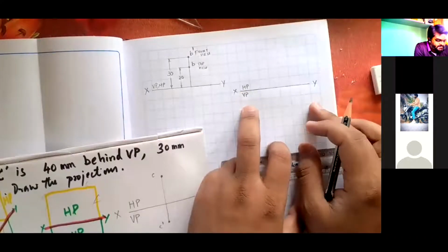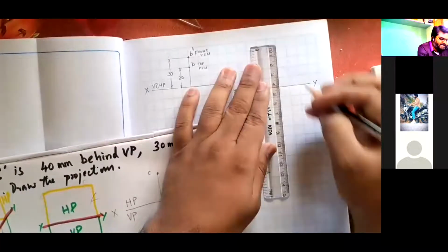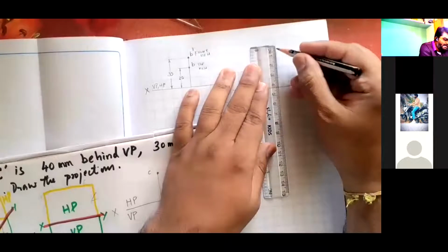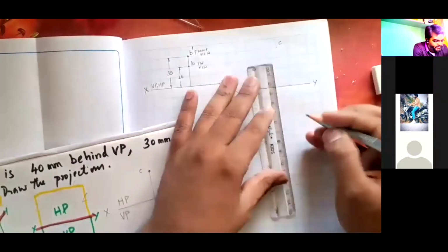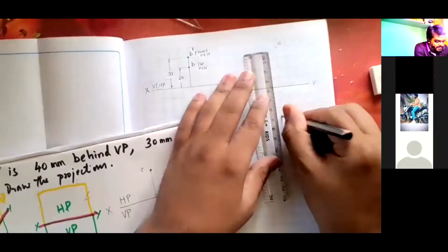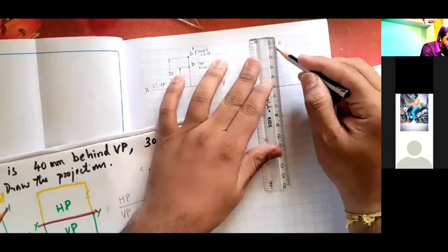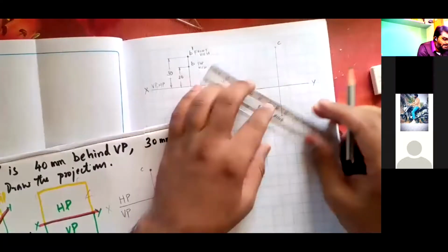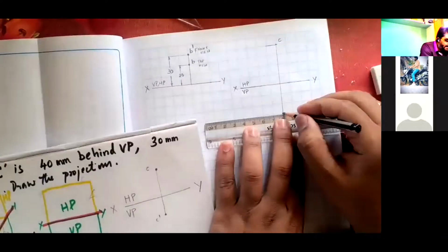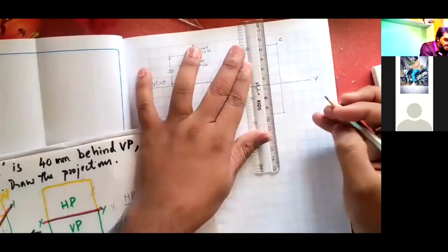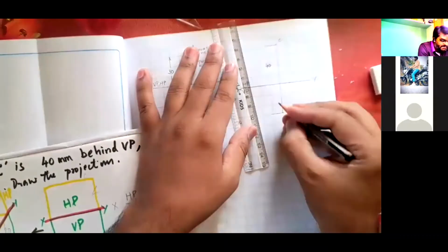So next is four boxes. Four boxes directly, I'm marking a point here as C, and three boxes on the same line I am going to represent and draw a thin line. Next, perpendicular lines are drawn to this line, here as well as here, and mention the dimension 40 exactly at the two boxes, representing half of the total dimension, and somewhere here I represent 30.